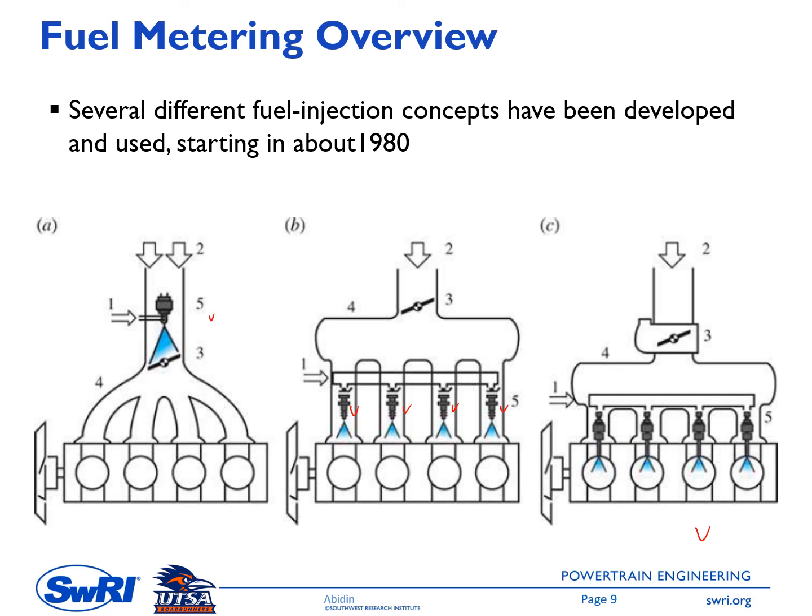A good thing for C, as I mentioned, is that it has a better transient response. And later on you will also see that C will have better fresh mixture cooling, which is good from the volumetric efficiency perspective.